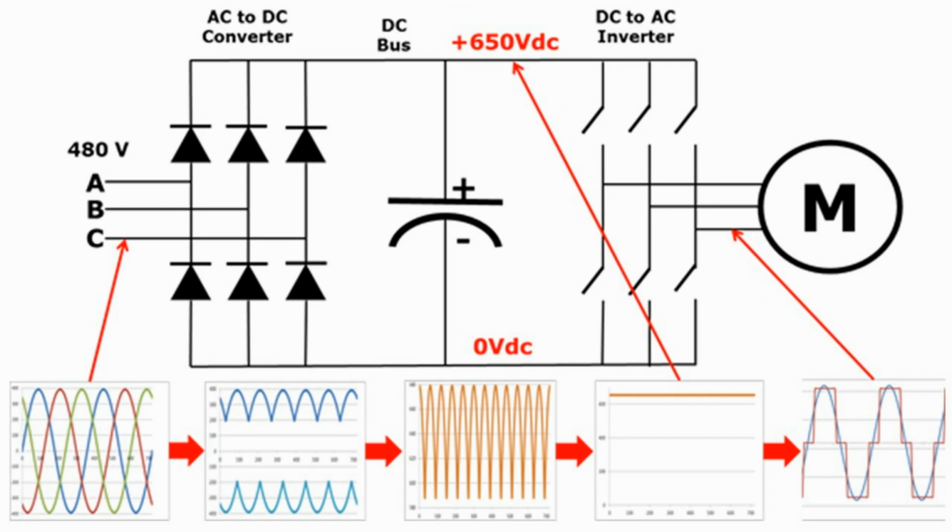Note that in a real VFD, the switches shown would actually be transistors. When we switch one of the top transistors in the inverter, that phase of the motor is connected to the positive DC bus and the voltage on that phase becomes positive. When we switch one of the bottom transistors in the inverter, that phase is connected to the negative DC bus and becomes negative. Thus, we can make any phase on the motor become positive or negative at will and can thus generate any frequency that we want.